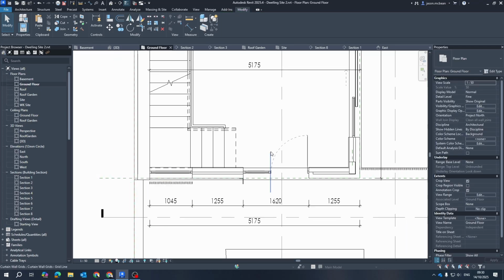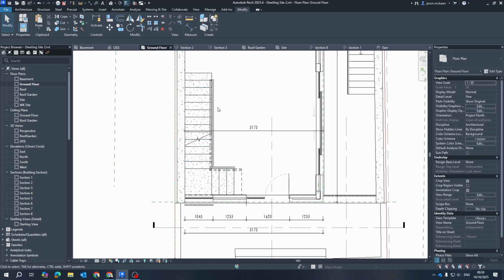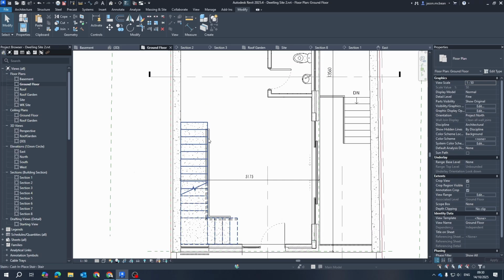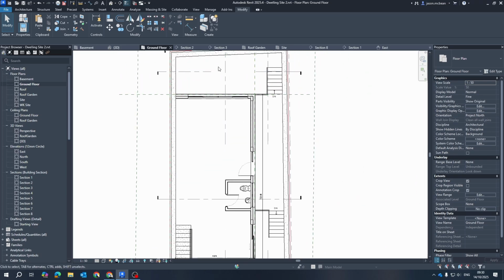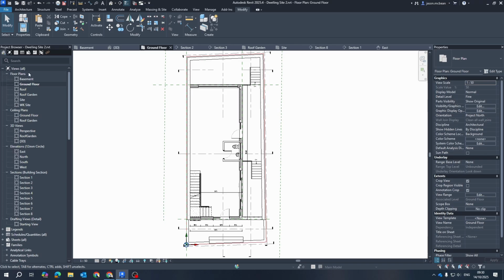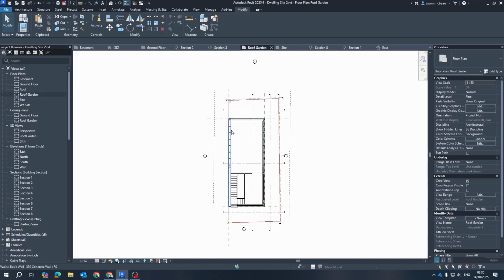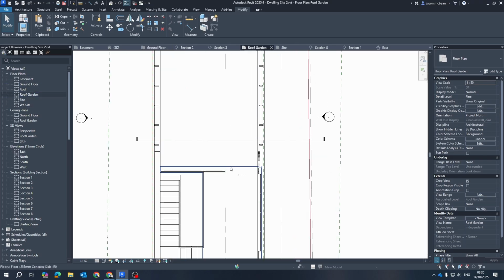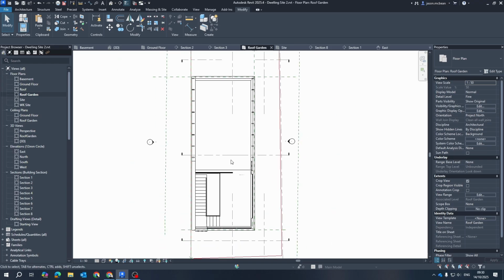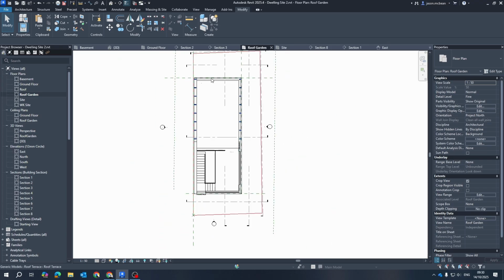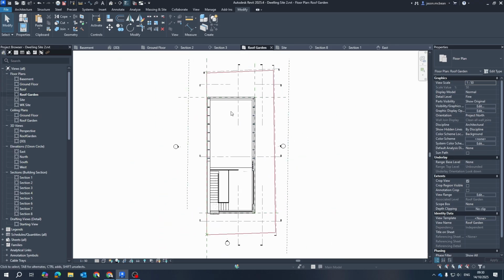So in Revit you can model some stuff, but not everything. The way the stairs work sometimes also depends on your view ranges, so it does get a bit complicated to get these views to look correct. Okay, that is the downside to Revit. It just takes a bit of work to get the floor plans to look as good as a drafted floor plan. Okay, so there are some downsides, but you do have a very complete model where you can just simply cut up what you want to see.